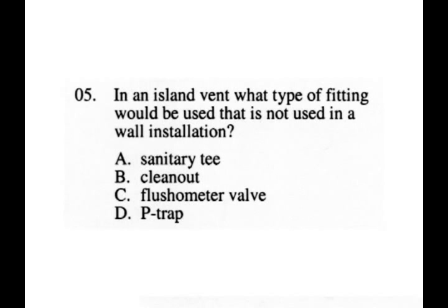Number 5. In an island vent, what type of fitting would be used that is not used in a wall installation? The answer here would be a cleanout, letter B. And a cleanout is required in an island because the vent runs under the floor. So a stoppage in the drain line might end up causing a flooding in the vent pipe, thus the cleanout is necessary.